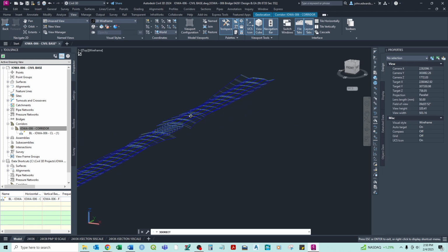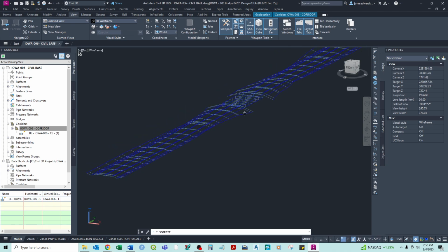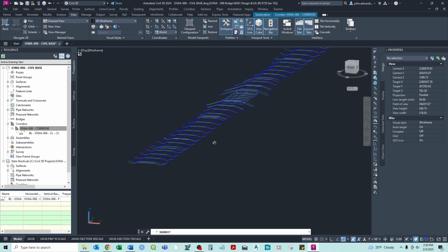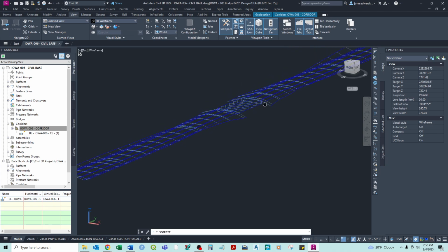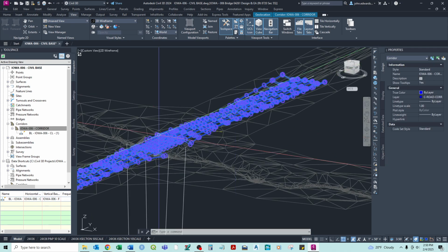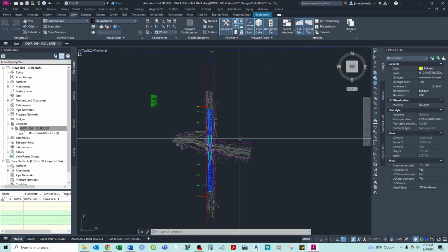And this is helpful to be able to view it in 3D sometimes, because sometimes we really lose sense of how we're doing it. We can see our plan view, we can see our 2D sections, which we'll create later, but being able to see and interpret this, that you can see from the beginning we're in a cut scenario where we're having to cut a ditch and come around, and then as we get to the bridge, now we're filling here, and then we come back into a cut section here. And that helps inform what it looks like. Okay, so I'll save this.